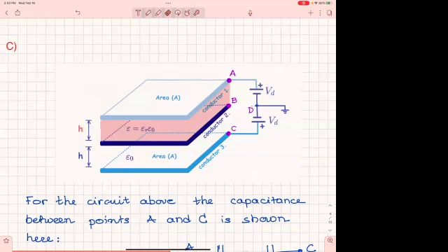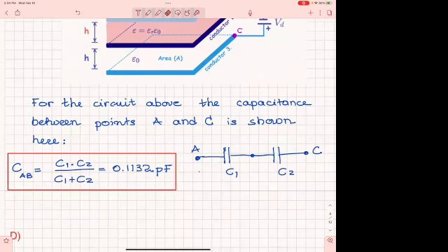All right, it's a capacity. When you say I have a capacity in this room of 150 people, the room a lot of times is empty. But the capacity is there. All right, the capacitor is the same. So you can have capacitance but not charge. The capacitance means that they are so close to each other that if there were charge, then I would see a field that is important. So 0 charge for this, but the capacitance exists. And how do I find the capacitance? From here? It's a series capacitance.